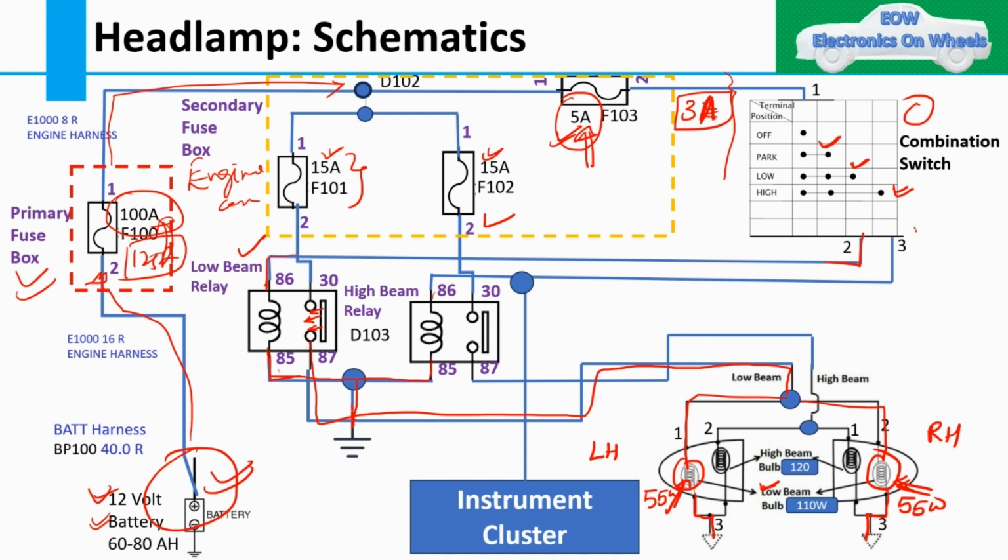Now similarly we will see the high beam relay. In the high beam relay we have this particular connection here from pin number 3. We are controlling this coil, and this coil will make and break this particular load connection. After that, this connection is going to the high beam, through the splice, and this high beam will control this bulb. This is LS side, this is RS side.